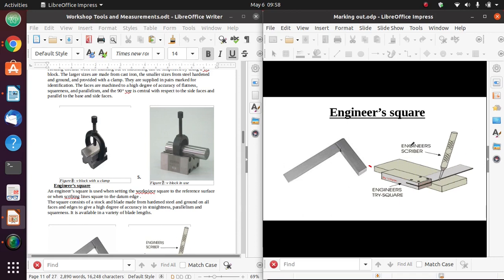I don't know if you're able to see the video that I sent. For example, if I'm drilling a hole, I'm using a vertical drill which comes from above, and I want to drill. This is my drill, and this is my workpiece. For me to ensure that my drill is at 90 degrees to my workpiece, I will use this tri-square, so that I don't end up using a drill bit that is at an angle.